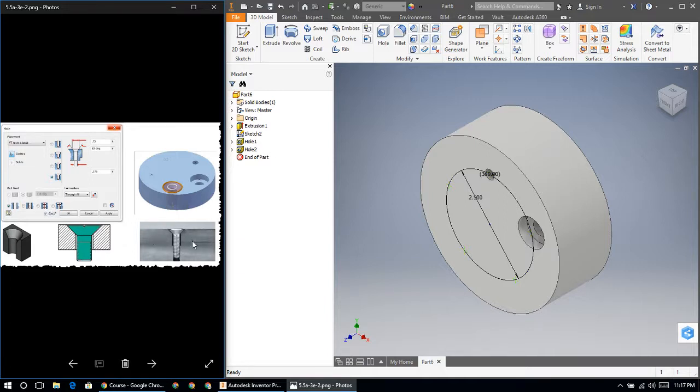A real life example, this part here is threaded. Think of this as 2 boards coming together or 2 pieces of metal. We've threaded the bottom one, and we are going to screw this bolt or screw into that bottom one, and the pressure that's created on this beveled or tapered edge at the underside of the head of this bolt will press down and be pulled down against the surface of this one over here, holding these 2 boards together, or 2 pieces of metal together.